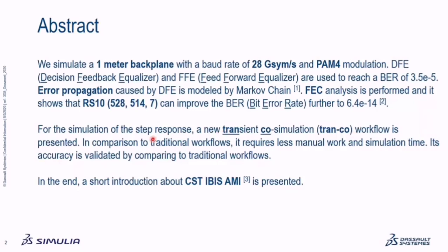We also present a new workflow to simulate the step response for the SerDes channel. In comparison to the traditional workflow, which uses S-parameters and macro modeling, we don't simulate the S-parameters. In this case, we solve the Maxwell equations and the circuit equation in the time domain and get the step response directly. In the end, we will show some capabilities of the CST AMI task, which was implemented in 2019, to show you some CST IBIS-AMI simulation capabilities.